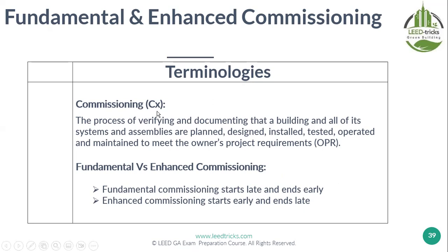It is a process including verification and documentation that the building and all its systems are planned, designed, installed, tested, and operated as per OPR, owner project requirement. Sometimes you bring a third party to do the commissioning in addition to the project team, of course, because this is critical. It's about the handing over process, testing, and commissioning.